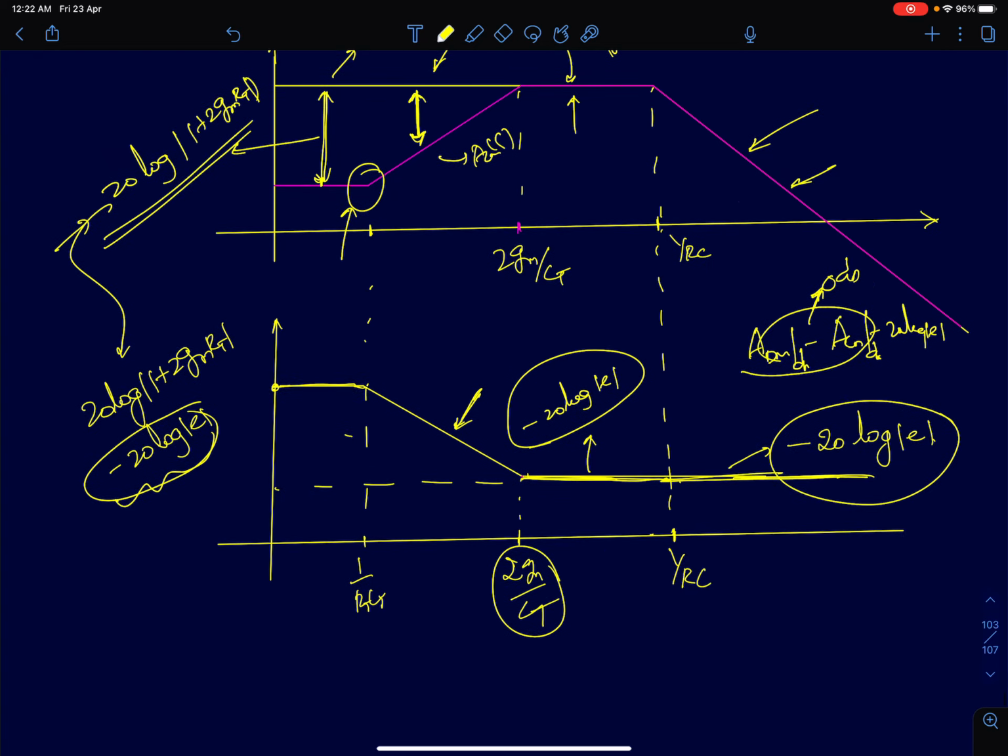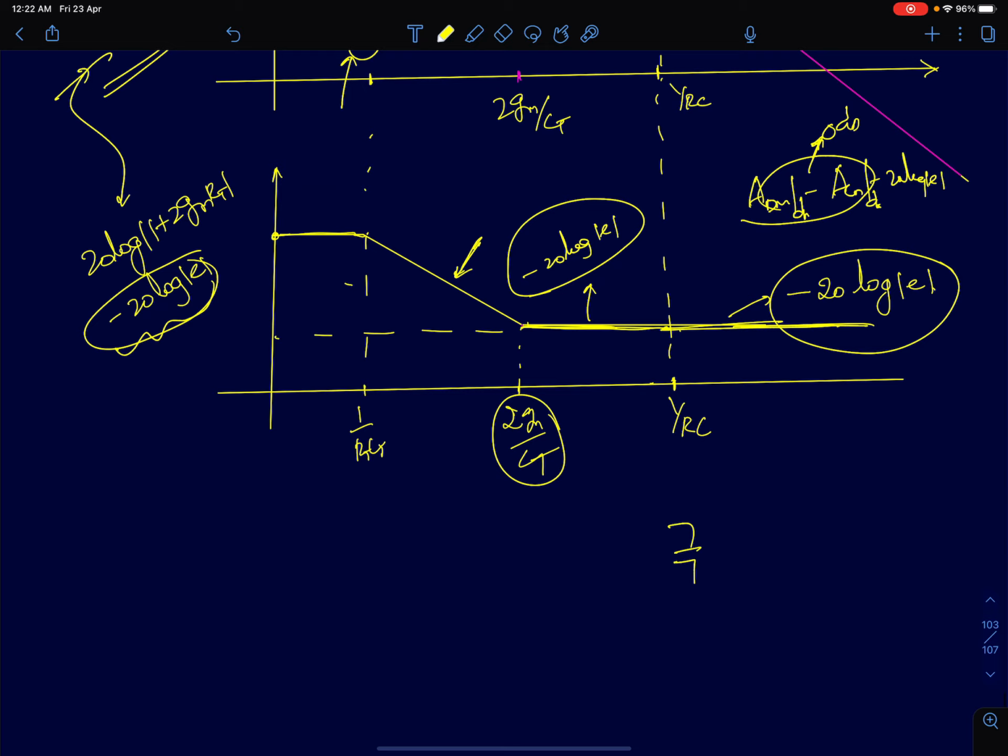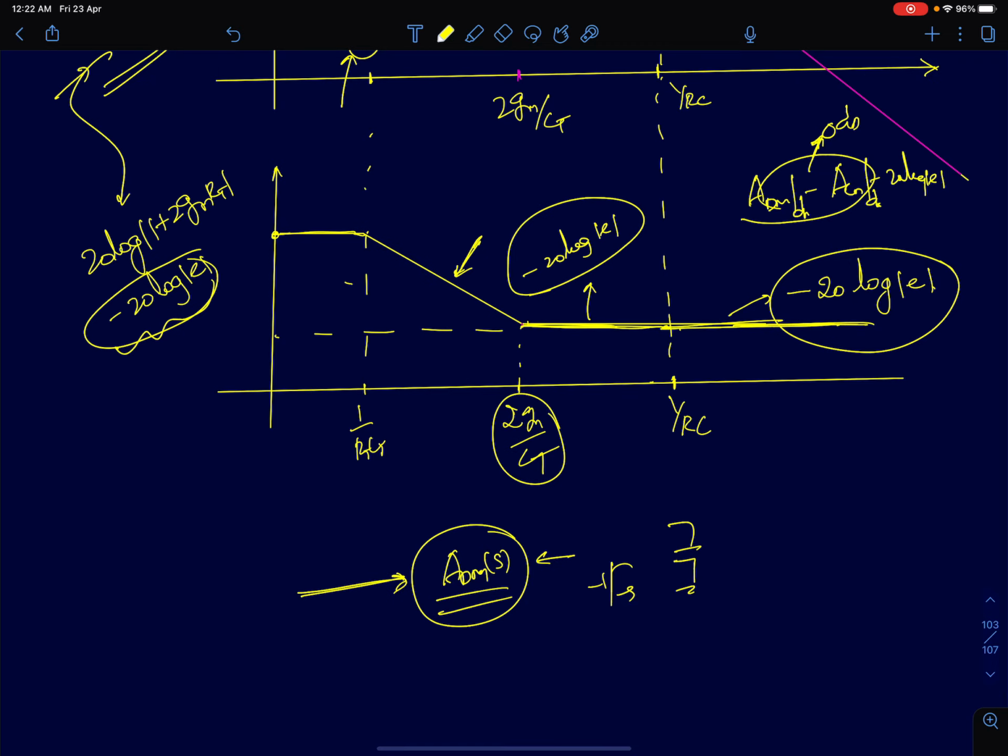So what we are noticing, the effect of this output capacitance C is that it has an effect on ADM. The differential mode gain starts decreasing because a pole is introduced in the differential mode gain transfer function. So differential mode gain starts decreasing at very high frequencies. So that's what we saw because of this capacitance. CT anyways had no effect on the differential gain.